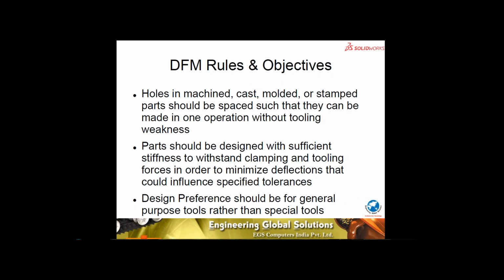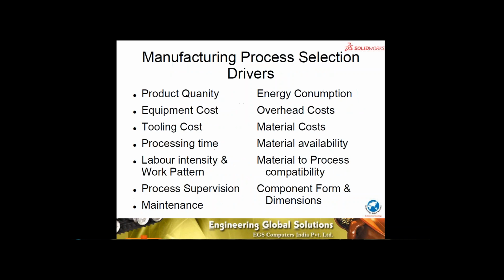Parts should be used with sufficient stiffness to withstand the clamping and the tooling forces in order to minimize the deflections that could influence the specified tolerances. Design preference should be given to general purpose tools over special tools, because those increase the cost.